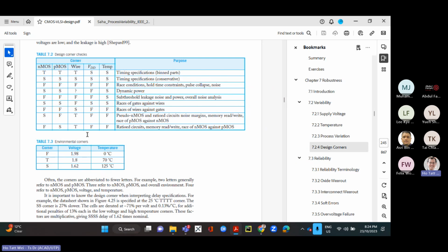And for VDD, the fast corner is when you actually have 10% higher than the nominal voltage. Nominal voltage is the voltage at which your process is supposed to run. So let's say the FinFET 7 nanometer process is 0.7 volts. The fast corner will be simulated at 0.77 volts, and the slow corner will be 10% less, 0.63 volts. And again, for temperature, the typical corner is actually at 70 degrees Celsius.